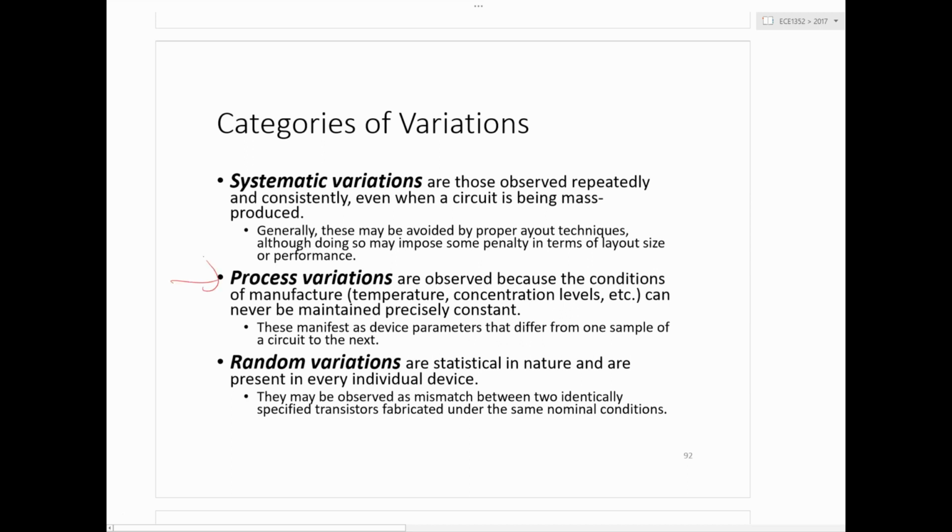Process variations are different. They arise from manufacturing variability, and those are really important. So you'll see that in the assignment, there are sections where we're going to require you to simulate your circuit with different process variations. The way that's handled in practice is that you have totally different device models. You have a set of typical device models that provides nominal values for all the parameters like Cox and mu and so on. And then you've got what are called fast and slow models, which vary all of those parameters in unison in whatever way makes the transistor a little bit faster or a little bit slower.